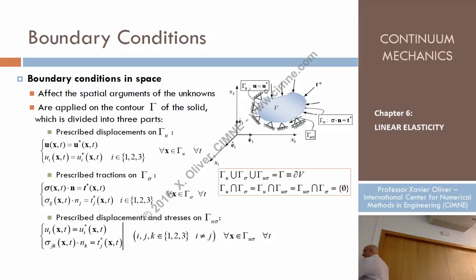There could be other parts of the boundary where I know what the tractions are. For instance, if I consider that point, if I put some forces here, not imposing displacement, at the points where I place the forces, I know them. The most general way of expressing the forces at the boundary is the traction vector, the force per unit of area. So there is another part of the boundary where I know the forces. This part can be that corresponding to 0 forces. For instance, on all these points here, there is no force applied. So these are points where the tractions are known.